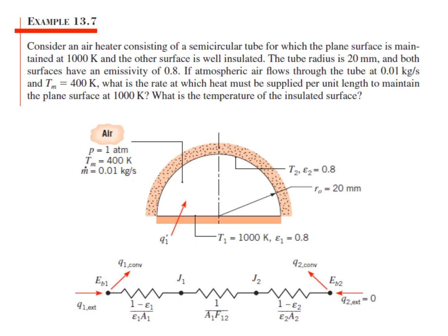So now I know that there's air flowing between the two surfaces, so it's not just a radiation case, there's actually a flow of air, which means that I do have convection as well. So when I'm looking at surface 1, which is my heater, I'm not only radiating heat off from the surface to the surrounding, I'm also convecting heat out. So heat is going to go from node 1, or the node for surface 1. It's not only going to be radiated towards the other surface, but it's also going to be convected. And that's what I'm going to assume on the bottom surface based on this information.